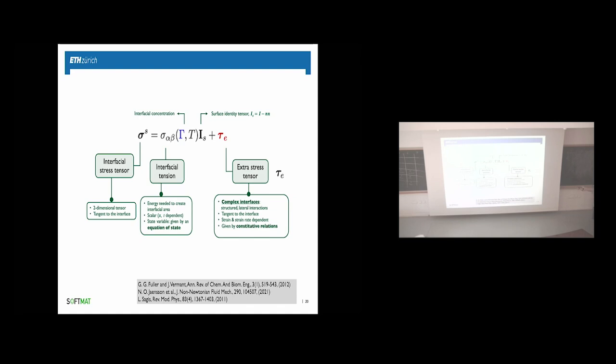And then I have my rheological stresses, my extra stresses. They come from structure at the interface, proteins interacting, the hydrophobins, for example, and they give you mechanics. They give resistance to shear, solid-like properties, right? If I get a shear modulus, I get solid-like nature, and they can be everything that Gareth promised you. They can be time-dependent, can be rate-dependent, can be strain shifting, everything. So there's a lot of fun to play with.